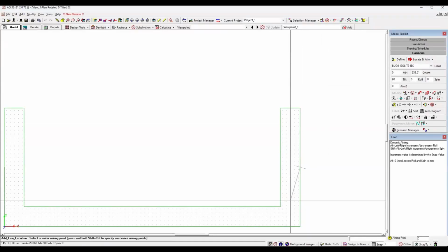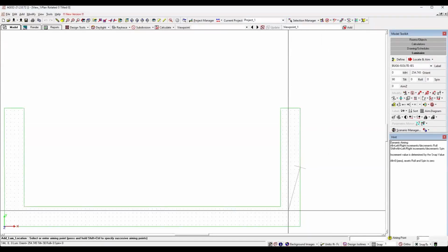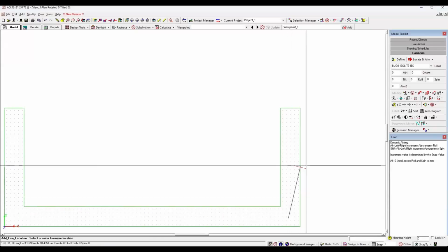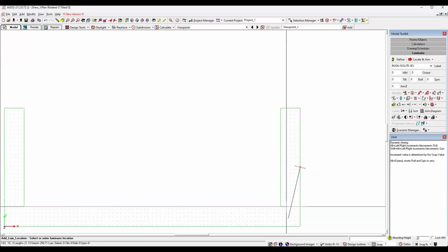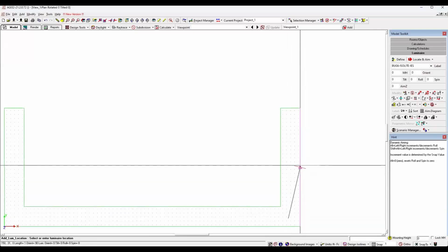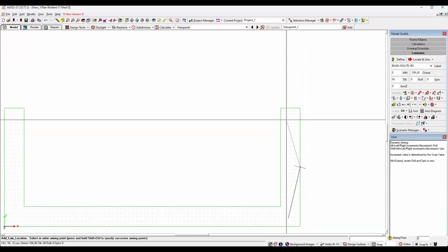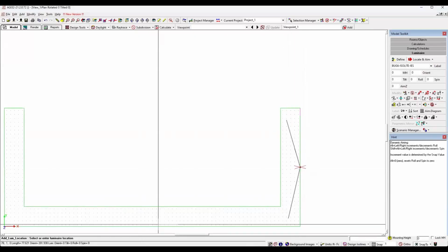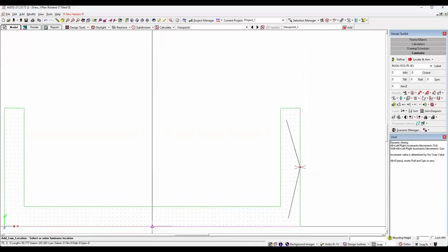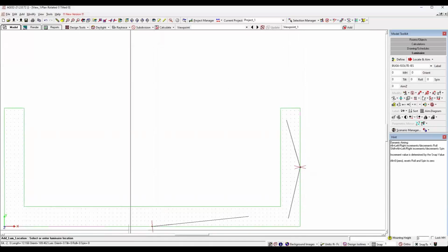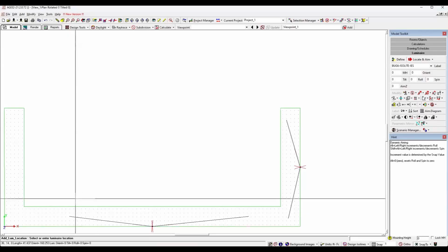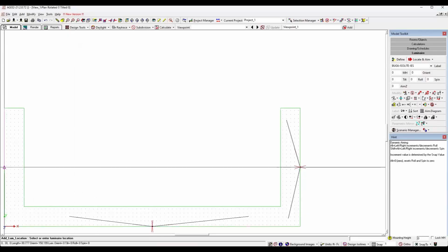I'm going to place one right here because I'm going to eyeball this and give it my best guess, and I'm going to aim it right here. So if you were looking directly into the bulb, it is pointed directly at this point on the ground. Well, we have 2 heads, so we get to aim one over in this direction. We're just going to try centering them on these walls as our first guess to see if that works and to see if we're able to meet code that way. Same thing for this wall. I'm just going to mirror the one on the other side.